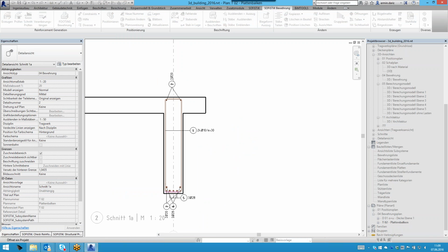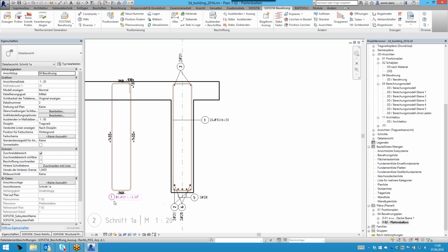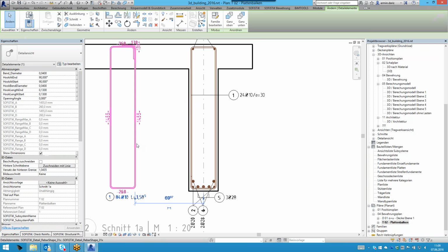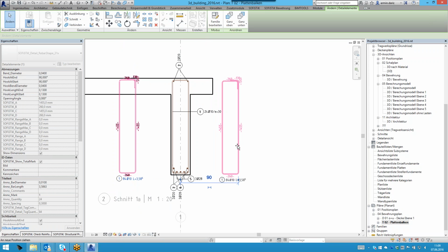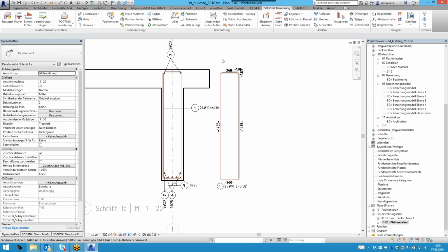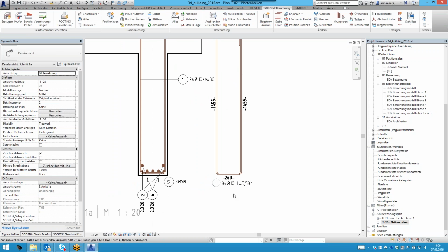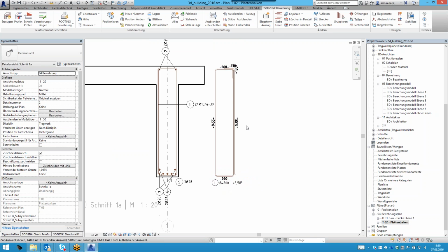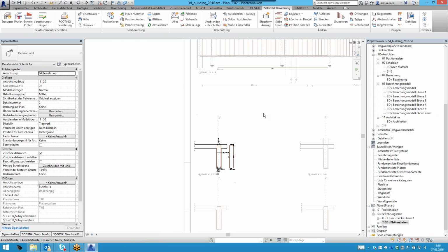a shape definition of your bar with all your indications of hook length, of segment length, and of the entire numbers of your bar. Okay, you can move that also on the right hand side. I think it's quite better to get also readable all these values. You see we get an indication of each segment length, and we have also an indication of the entire length and of the number of the bars inside this for this bar mark.